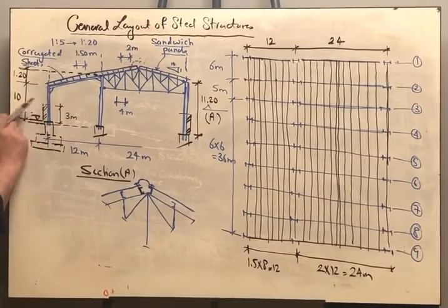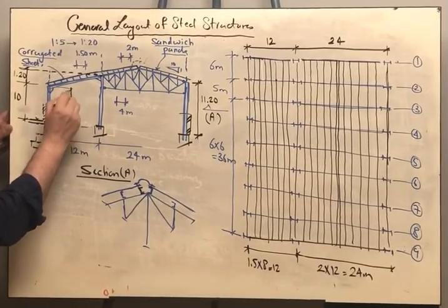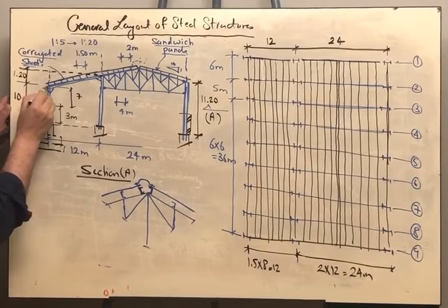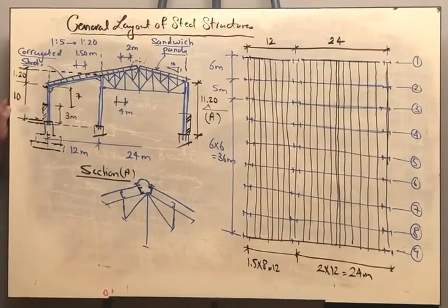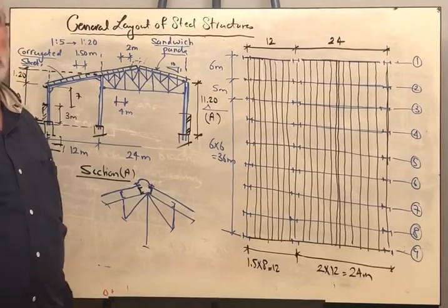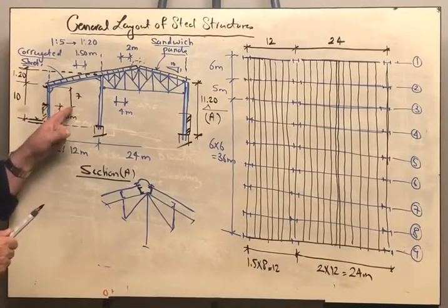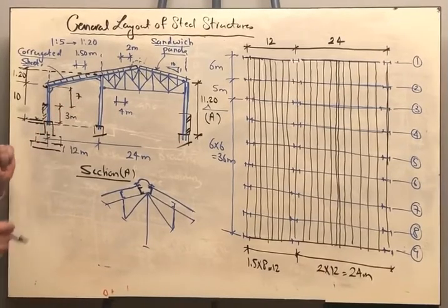There remains from the 10 meter, we are having this part here is 7 meters. We have to put a purlin on this edge and a purlin over the brick wall, and the spacing here is 7 meters. Of course, it is too much for the span of the corrugated sheet. We have to divide the 7 meter such that the spacing between the side purlins is ranging from 1 to 2. We can divide this into 4 equal spaces. So if you divided 7 over 4, it will give us 1.75.